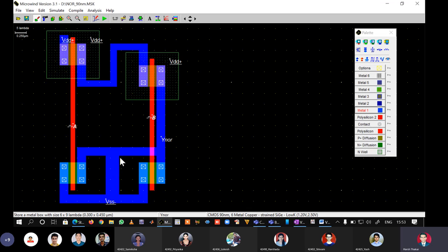Now I told you that every layer, whether it is polysilicon, polysilicon 2 or any metal layer from metal 1 to metal 6, has a characteristic sheet resistance, that is, it exhibits a non-zero resistivity. So this kind of fault, wherein the output node gets connected to either the VDD power rail or VSS power rail through elements such as metal blobs, is called a resistive short.